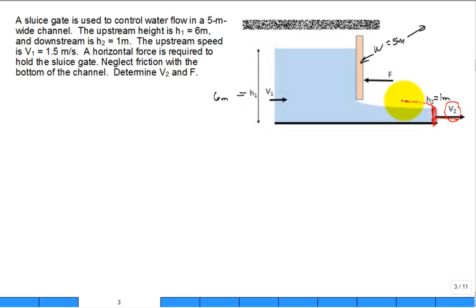So why is coming in here and cutting not so good? I see a lot of people put this, very, very common: the pressure distribution on that boundary of the control volume. Well, they're thinking it's the pressure distribution on that part of the wall. But take a look very closely. What is the pressure right here in the water? Atmospheric. What's the pressure up here? Atmospheric. What's the pressure here? Atmospheric, atmospheric, atmospheric. What is the pressure right there, if it's where some air is? Atmospheric.